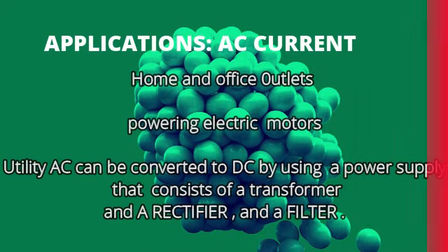This is because generating and transporting AC across long distances is relatively easy. At high voltage, less energy is lost in electrical power's transmission. Higher voltages means lower currents, and lower currents means less heat generated in the power line due to resistance.